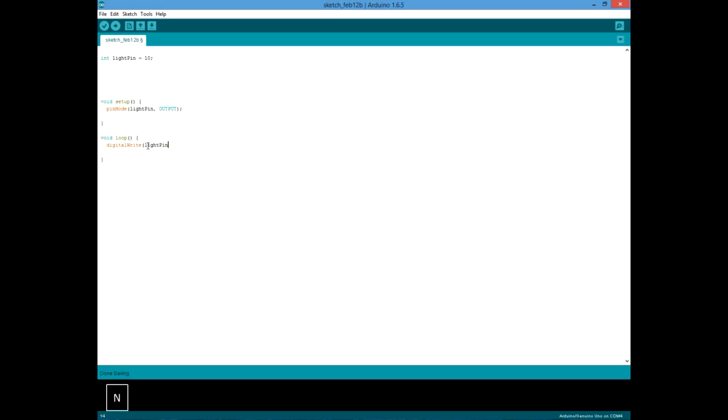Now I'm going to use our variable again. Here we could have put 10, but I'm going to use the variable, and now I'm telling it to write HIGH, or turn it on. And that's all we really need to do for this. After we verify it and upload it to the board, it's going to ask us to save first. But after you do all that, if you set up the circuit or one similar to the one that I'm using, it will turn your light on, and it will keep it on. So that's really the basics of digitalWrite.